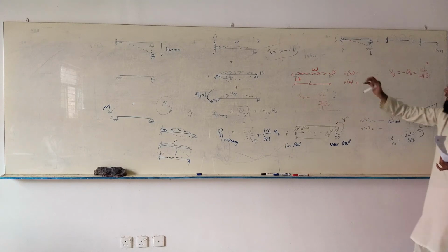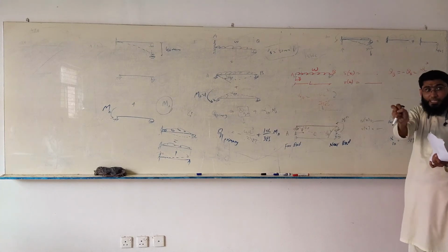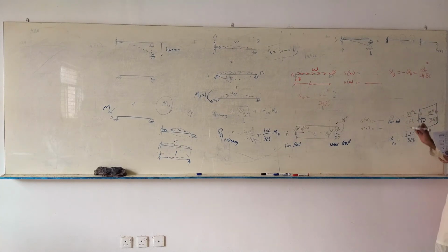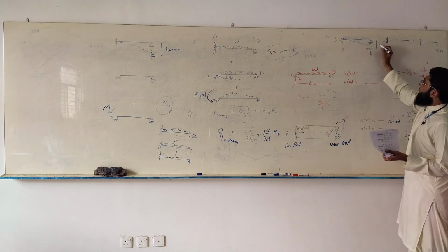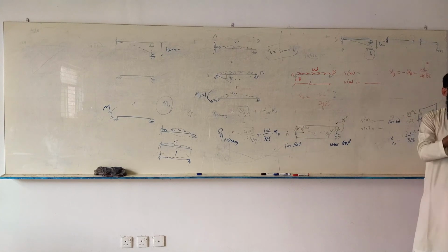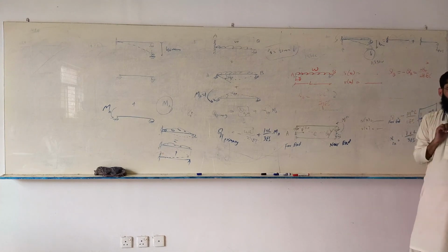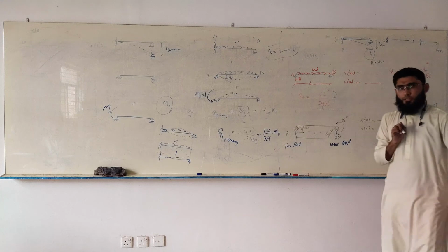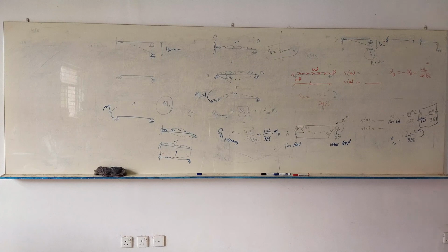You remember these results? We had certain direction over here, some direction over here, and some more direction. There is no loading. There is just settling. What does that actually mean? In the given situation, you are given a certain displacement, for example, 40 millimeters downward, and they tell you what the direction is over there. This is what you found last time. I think this answer was 103.3 kilonewtons or so. Clear? Do you remember this result? The displacement was 40 millimeters downward, and I think it was, can you confirm this, 103 point something kilonewtons? That was the reaction at B.